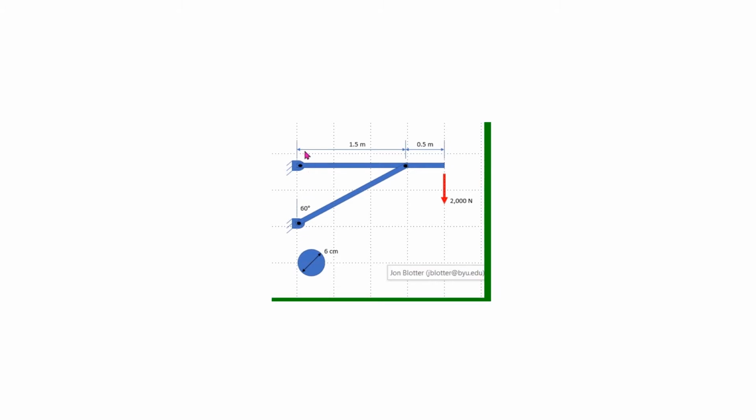In modeling the boundary conditions, we will fix all three displacements at the left ends of the beams. We will also fix all of the rotations at these locations except for the Z rotation, which we will leave as free. To properly model the connection between the two beams, we will need to insert a joint. The joint will be able to translate and rotate in the global coordinate system. However, the translation in both beams at the connection point must be the same, and this condition will be provided by using a general joint.